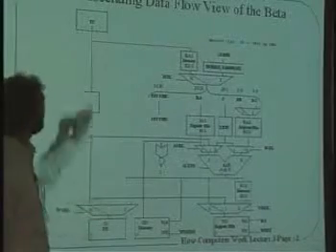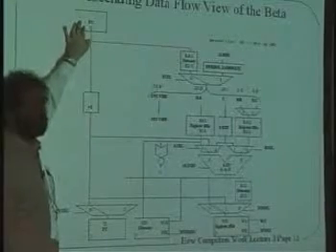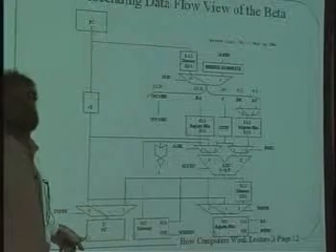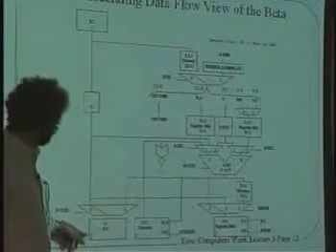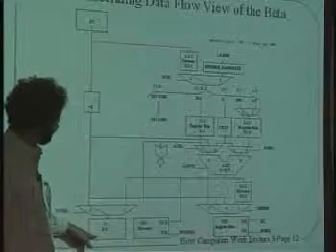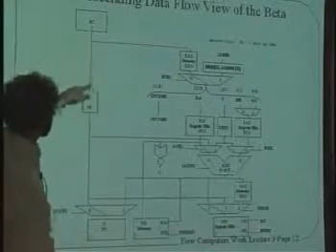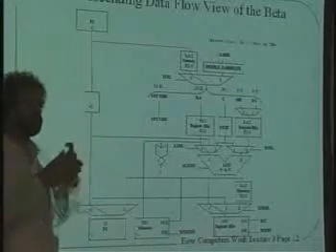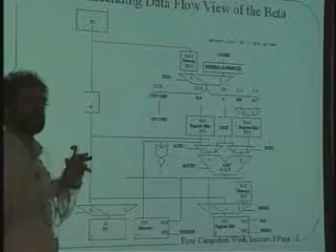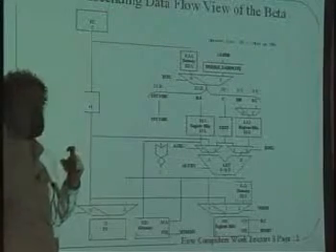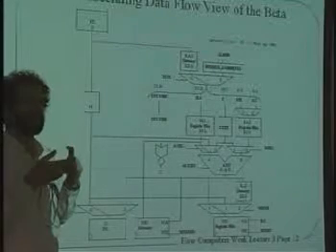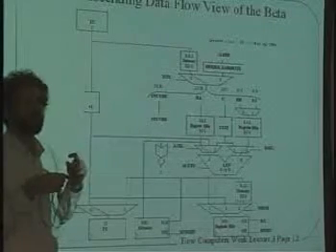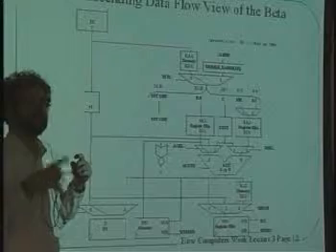And what is the result? If the PC had a particular value in it, n, before, when this clock goes off, what will be written into the PC is n plus 1. Okay? Now, notice that as soon as the clock goes off, n plus 1 begins to race around here and turn into n plus 2, and then pretty soon what's in front of the lens of the camera, which just took a picture of n plus 1, suddenly morphs into n plus 2. And so you may think to yourself, oh my God, did it take a picture of n plus 1, or did the data run around and become n plus 2? Or maybe n plus 3 if it went around a few more times, or n plus 4, or n plus 5.